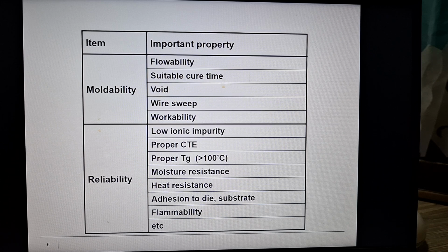And then we talk about what is a suitable and proper curing time, because each material requires a certain time in order to fully cure. Cure is triggered by temperature and by the catalyst or hardener that is used in order to react the components within it. Right? So it's called cure time, when you need time to fulfill the total reaction of the chemical.